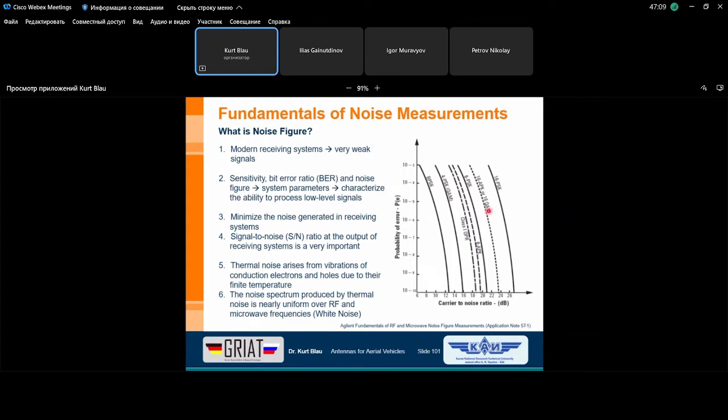We have 2 different magnitude states additional to the 8 phase states. Together, it's 16-QAM, quadrature amplitude modulation. And here we have 16 phase states, which means again the phase difference between these two is halved, it's only 22.5 degree. This is, let's say, the ideal case, but in practice it's smaller or larger, depending on the error.